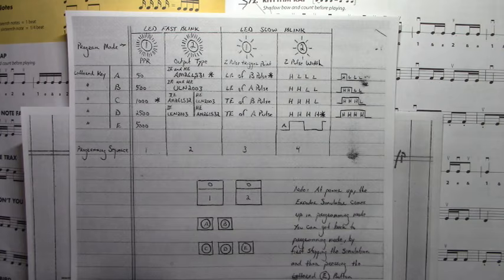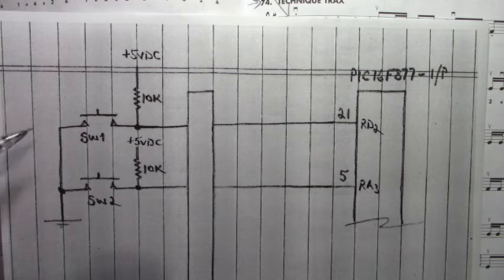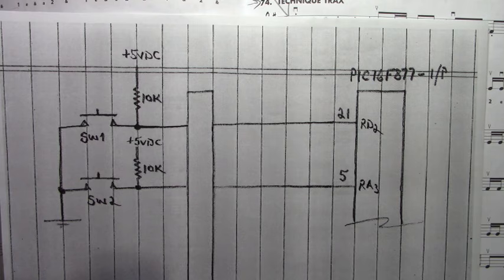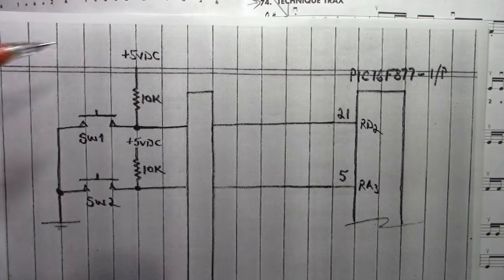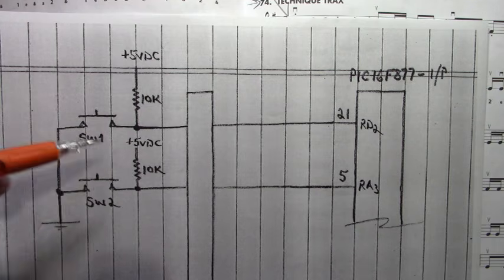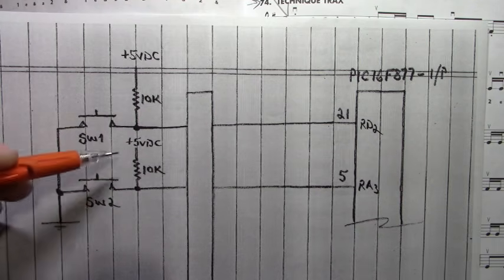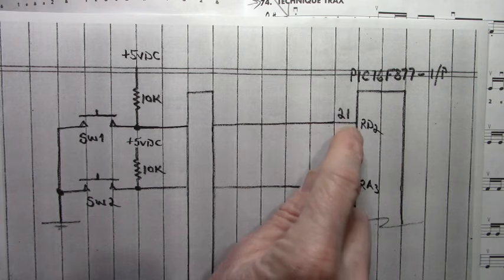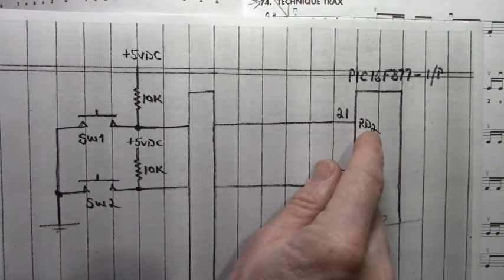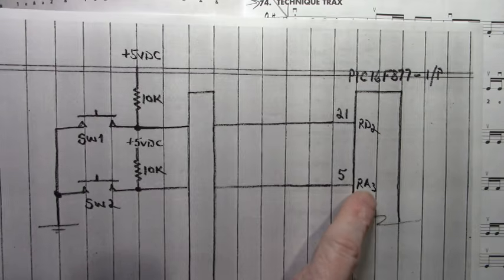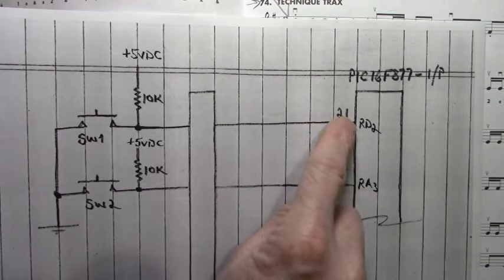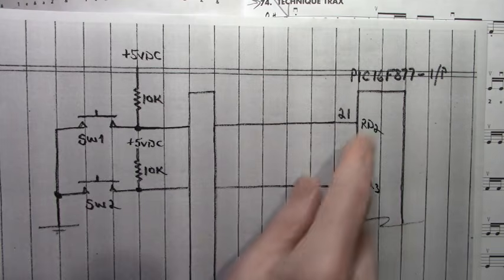But let's look at the switches and the buttons now, the actual circuitry. Here are switch number 1 and switch number 2. These are the switches with the blinking LED internal to that switch. So we have a 10 kilo ohm pull up here and a 10 kilo ohm pull up here, pulled up to 5 volts. And so at that point right here, port D2 and port A3, that's pins 21 and 5 on the PIC16